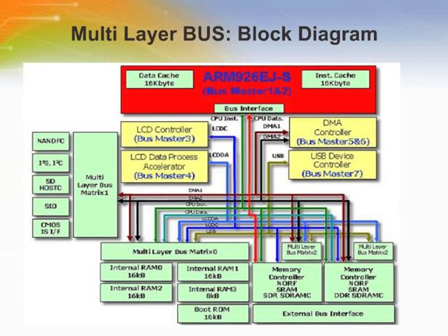Additional built-in peripherals include a 10-bit analog-to-digital converter, 6-channel 16-bit timer, watchdog timer, a real-time clock, and alarm functionality. The ARM926EJ-S 32-bit RISC CPU core deployed in the TMPA910CRAXBG offers flexible size instructions and data caches and a memory management unit.